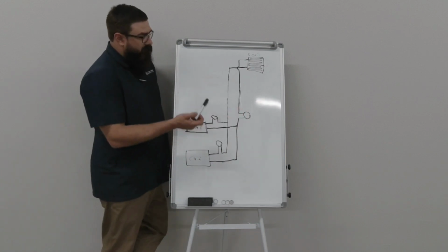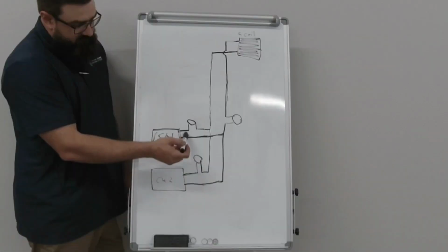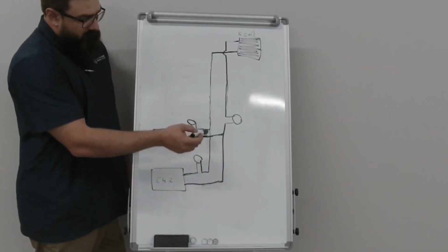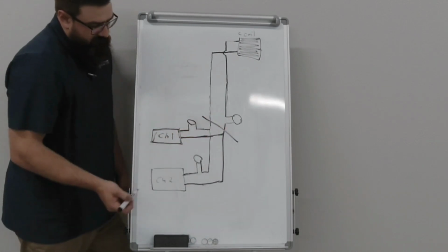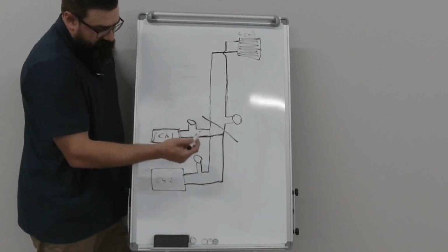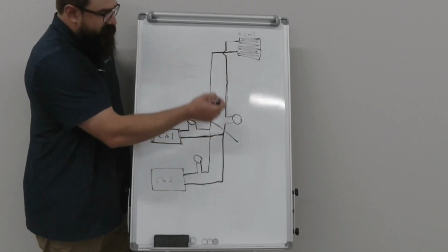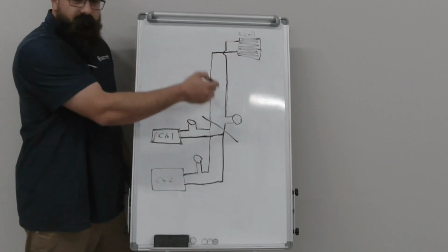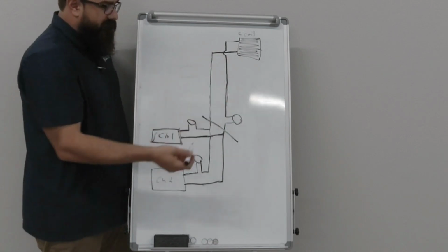So if you've got load, but you need to maintain differential pressure across your chiller, you can have basically two systems. You've got your chiller system, which is doing its thing, maintaining its differential pressure across the chiller. And then we've got our building system, which maintains flow and differential pressure, or whatever it's configured to do, through the building itself.